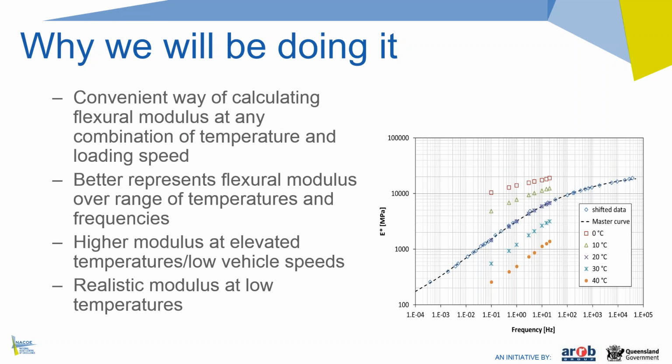So why are we doing that? Well, first of all, that will give us a convenient way of calculating flexural modulus at any combination of temperature and loading speed, but it also at the same time better represents the flexural modulus over a range of temperatures. So instead of taking a measurement at a single point and then assuming or estimating the performance of the material over a whole range of different temperatures and load frequencies, we're actually measuring it and characterizing the material over that range.